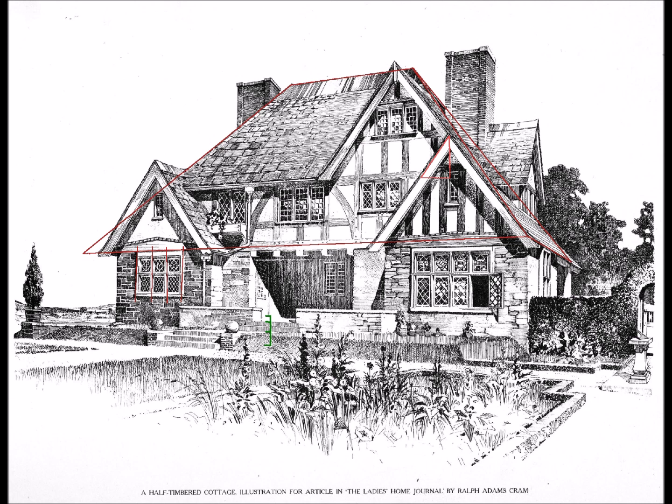So it looks like if we could see the left side and the back side, we actually have a roof that comes down to the top of the first floor. It's really a single-story house with a lot of roof. And then what they've done is sliced away the front part of all of that and exposed the second floor to bring in some windows. So I'm going to start by building a mass that's single-story with a large roof and then cut away, just like I described it.